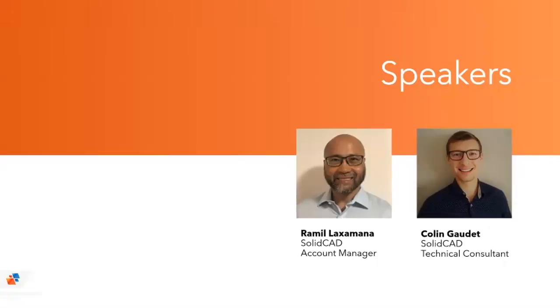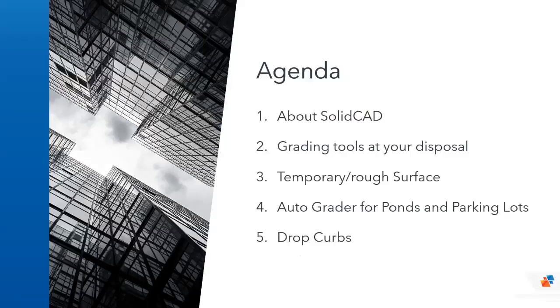By defining parent feature lines such as gutter lines, pond types, pond tops, or even right-of-way lines in subdivisions, AutoGrader allows you to create grading families to generate and update the subsequent child feature lines. When you make changes to your parent, with just a click, AutoGrader will automatically update child lines in a matter of seconds. But first, here's our agenda.